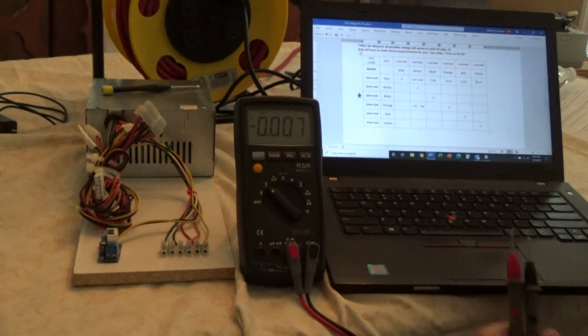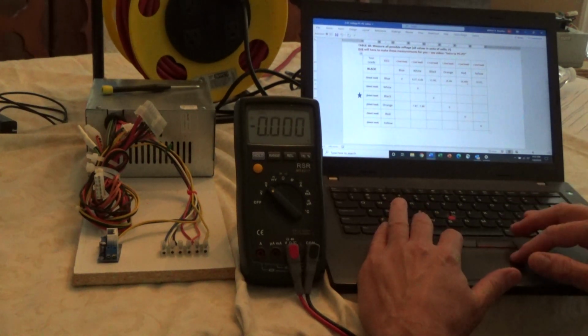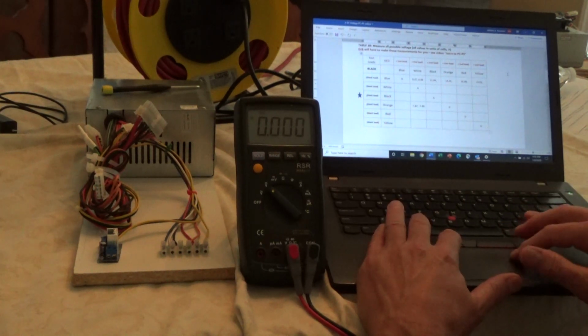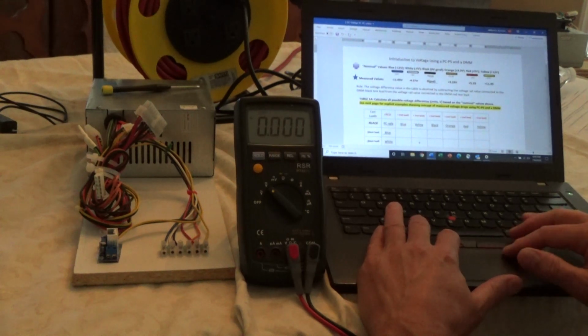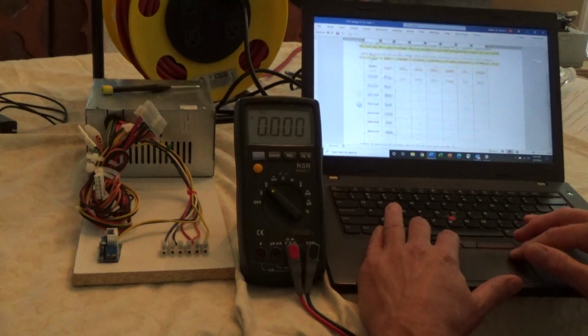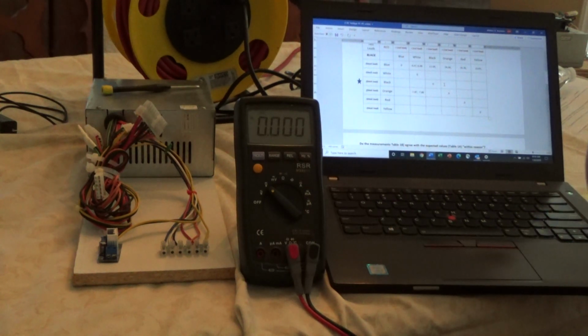Now I'm going to put commas in here. Now what do you have to do? Beside that, you have to go up at the top again and calculate based on the measured values with respect to ground. Just take differences, right? Red probe minus black probe. Now, that's pretty straightforward, I hope. I'm not going to write down anymore. You should be able to watch this video and pause it as needed and do the rest of them.